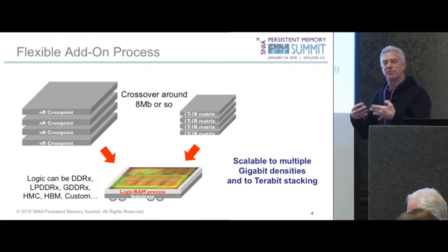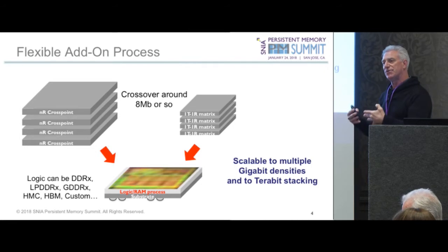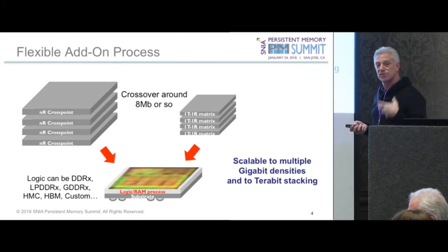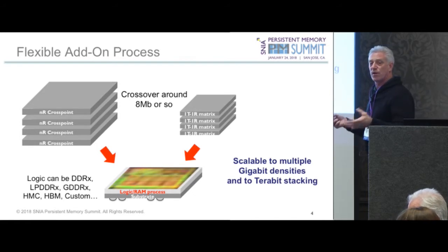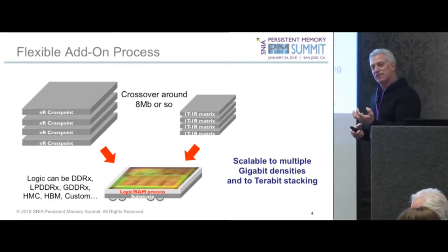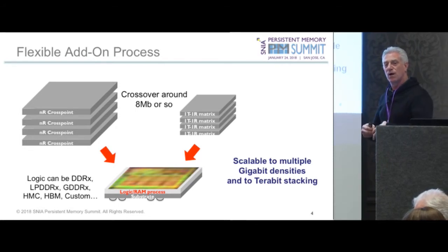And so the definition of persistence changes. The amount of energy that you need to supply is going to be very different based on what architecture you apply. So that is the problem that we want to solve. So, a couple of solutions here. One is to make a high-density cross-point architecture, which is essentially a main memory that is inherently non-volatile. The other part of the solution is that carbon nanotube memory can be put into a 1T, 1R matrix for smaller arrays to be dropped down onto controllers, because the memory that's in the controller also has to be saved somewhere. So if you had a controller memory that was inherently non-volatile, power fail presents no risk to you and no latency on power fail for recovering your system.